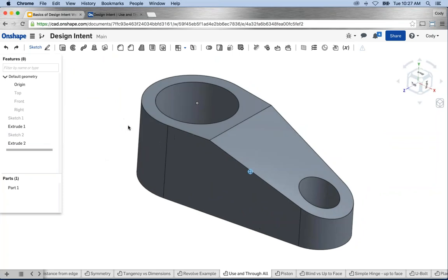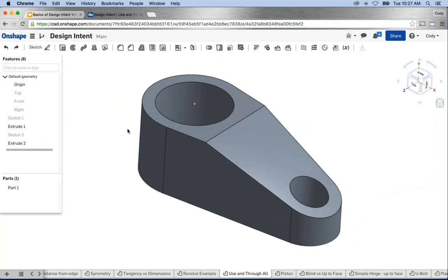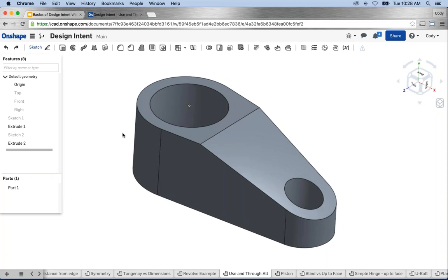The problem with that symmetric end condition is it's driven by a single value, 1 inch. It doesn't update, it doesn't know that the part has changed, so that 1 inch value is static. It doesn't react to changes. So again, this is an example where the symmetric and then 1 inch value gets me in trouble. And let me explain why.